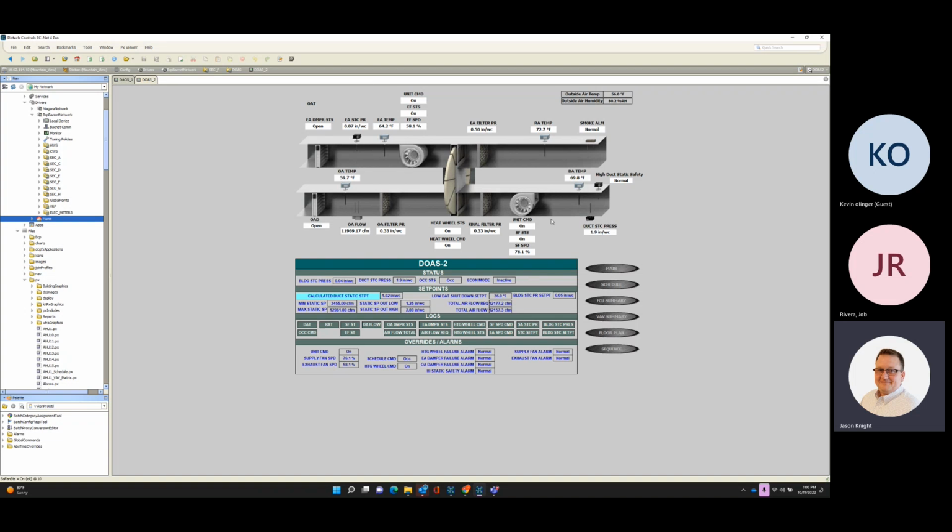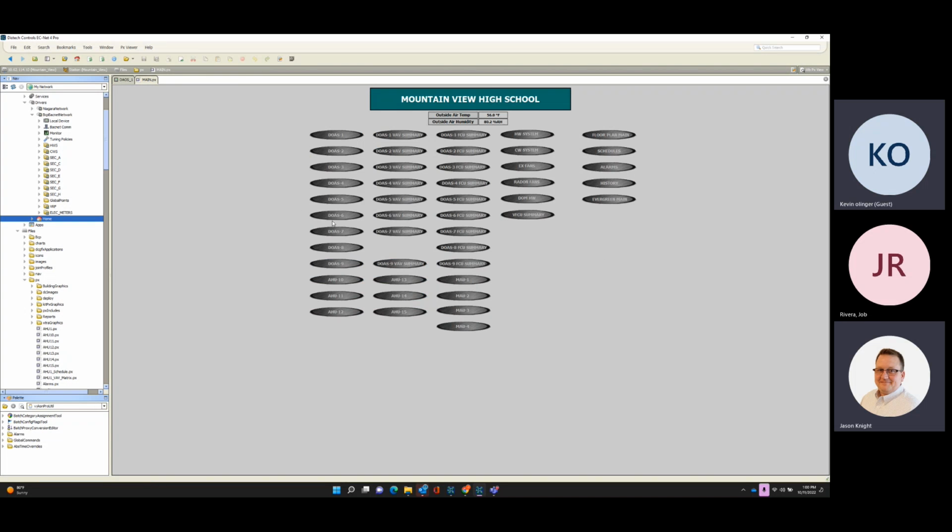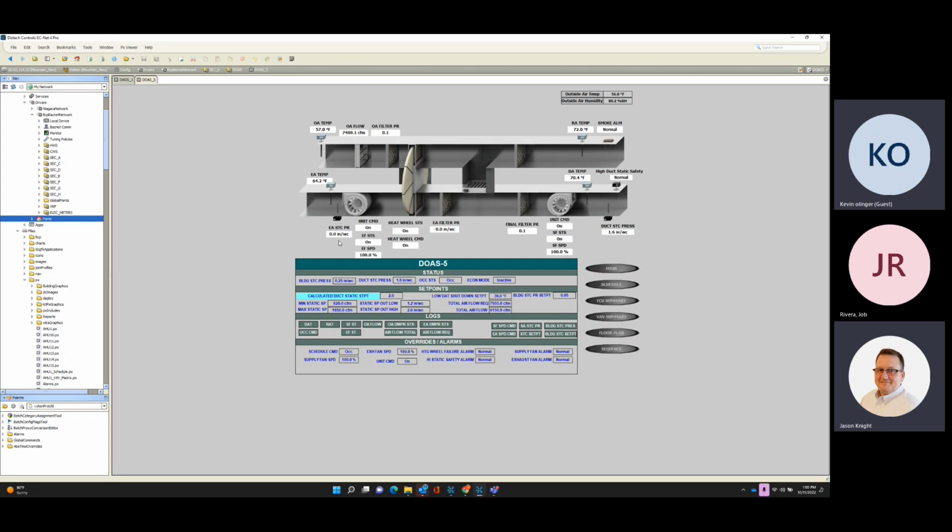So there may be one or two little things, but the overall operation and how it's sucking and pulling air is laid out here. But you will see a difference when you start looking at 5 through 9. Your wheel is back further. You have a bypass duct. The airflow station's over here.